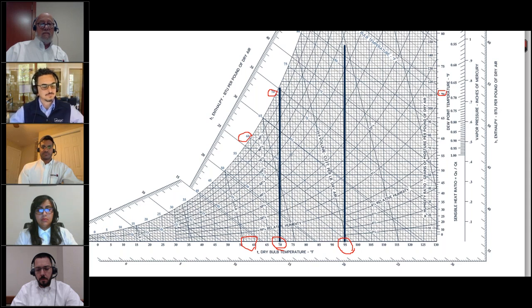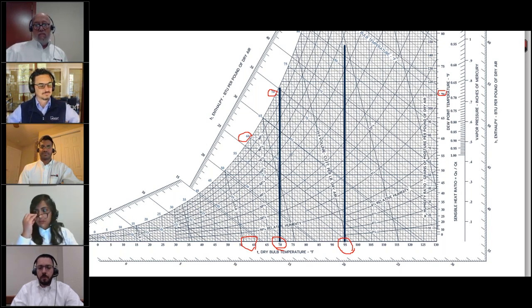All right, next one. I'll just ask a couple more before I let you return to your presentation. Are there charts that are extended to very warm temperatures? If I have a stack at, say, 220 Fahrenheit, how do we find the air properties? That's what I was referring to. In a flue gas stack, if it's flue gases, you can use a stoichiometric chart. There are high temp psychrometric charts. So if that stack is just air, if it's exhaust air, say out of a building, or high temperature air for drying processes, there are high temperature psych charts that extend beyond the standard 130 degrees that a conventional psych chart runs out to.